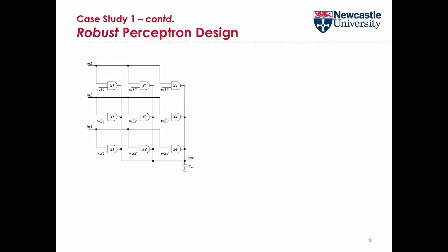Then we started doing a bit more work. We started developing a real perceptron, a 3x3 perceptron. The whole idea is that instead of using the single inverter, we use two back-to-back inverters with a little bit of smart connections between them, something like an AND gate. One of the inputs for the AND gate would be the zeros and ones defining the different bits of a weight. The other input will be the duty cycle of the inputs, so duty cycles define the different inputs. Input 1 will be a certain duty cycle, input 2 a certain duty cycle, input 3 a certain duty cycle.